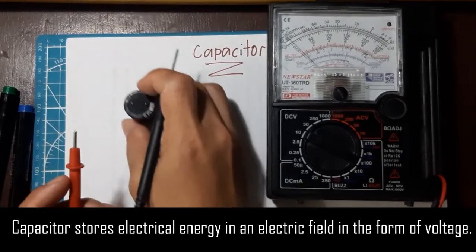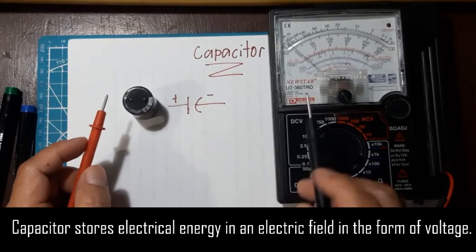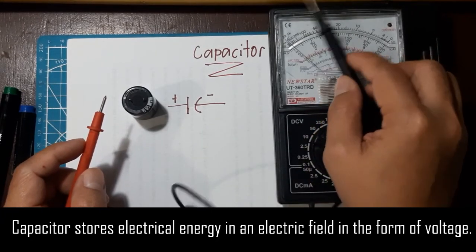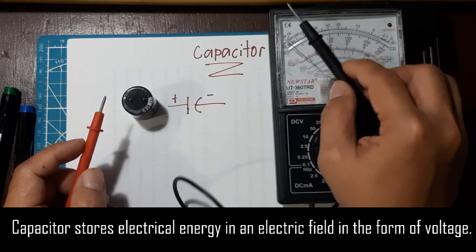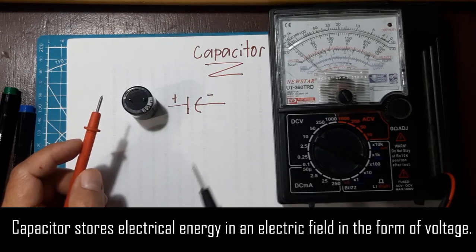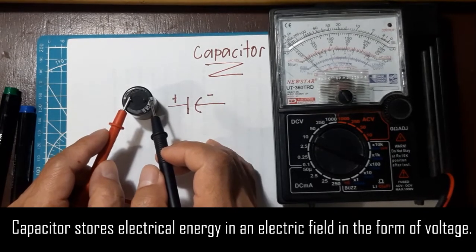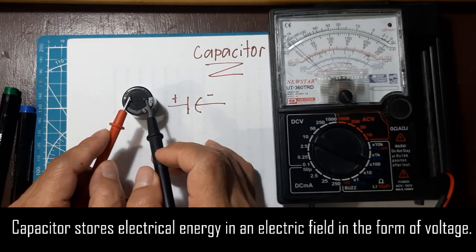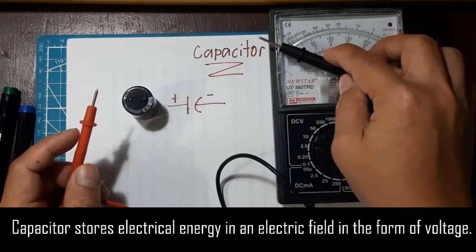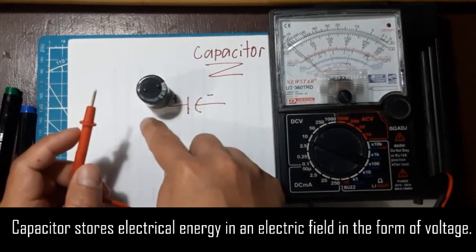To test our capacitor, it should again deflect and go back to infinite resistance. That should give us the idea that our capacitor is in good working condition, right? So let's test. See, it goes back because it stored the energy and it released the energy. So we can say that our capacitor is in good working condition.